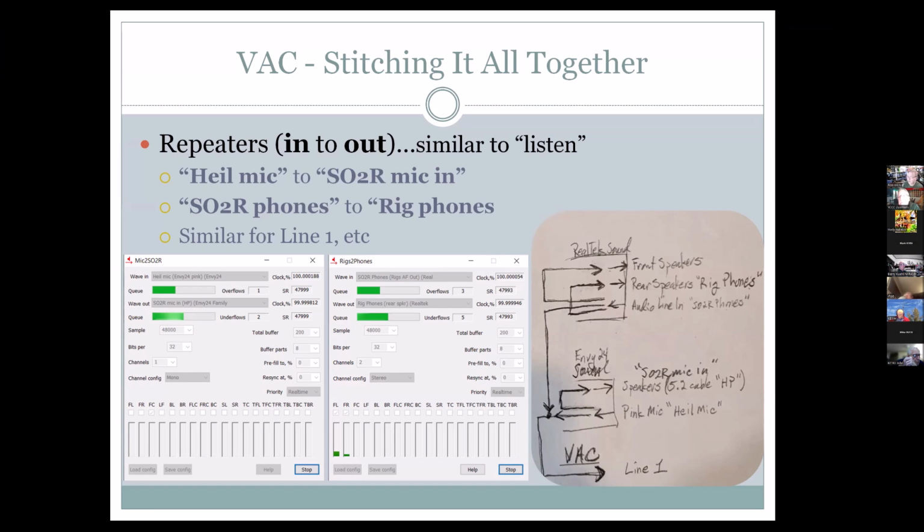So if you're sampling at 8 kilohertz, when you go to sample a piece of that audio data, you're throwing it into 32 buckets and then filling up a buffer. And it takes a while. Your latency ends up building up pretty quickly. So you can easily get half a second of latency built up when you're running at a slower clock rate.